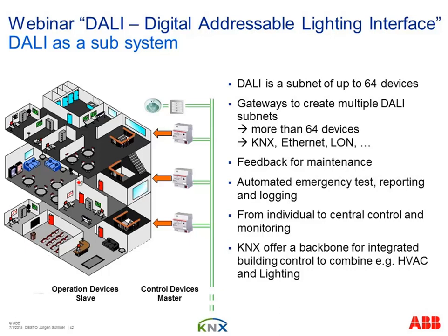And all these maximum 64 slaves can send back their status, whether they are on or off, and the brightness value, and additionally the master can monitor all the 64 devices, and so we know the status of the 64 ballasts. If there's for example a lamp failure or ballast failure, then we have the information here on KNX, and then maybe we can trigger an alarm message, or when you have a visualization, pop up a window: please replace the lamp on floor number 5 in this room. So we integrate all these advantages of our DALI system into our, for example, KNX system.